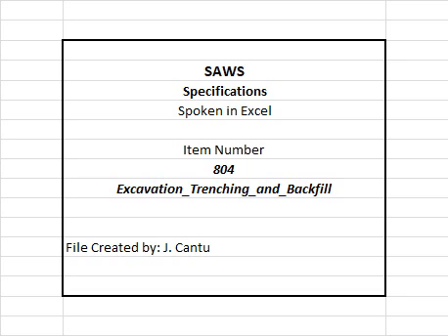Unidentified archaeological sites. 1. The contractor cannot begin excavation again without written permission from SAWS. 2. If more than 3 days are required for investigation, not including holidays and weekends, and the contractor cannot work on other project scope items, the contractor will be permitted to negotiate for additional construction time through a request for information, RFI. The RFI shall be submitted within 10 days after date of the first notice. Additional standby time will not be considered. 3. If the time required for investigation does not exceed 3 days for each event, contract duration will not be